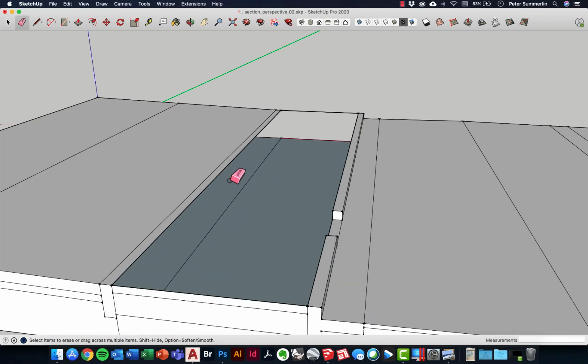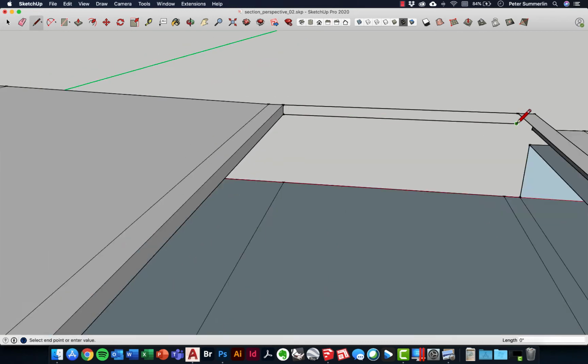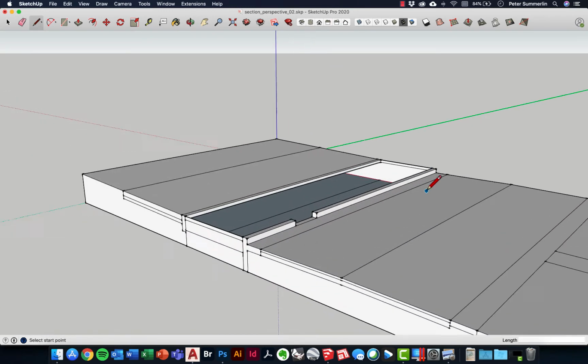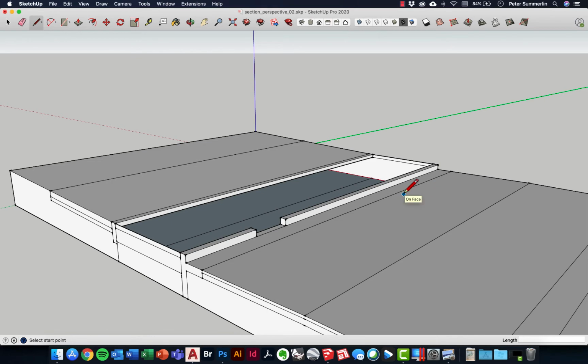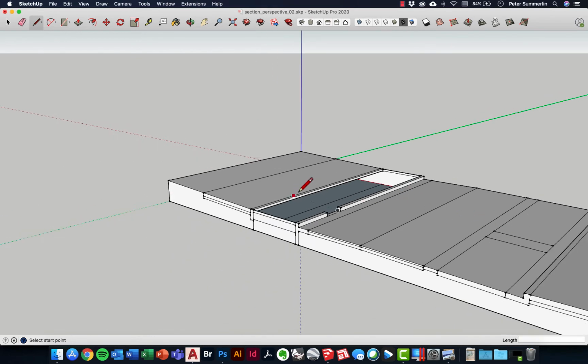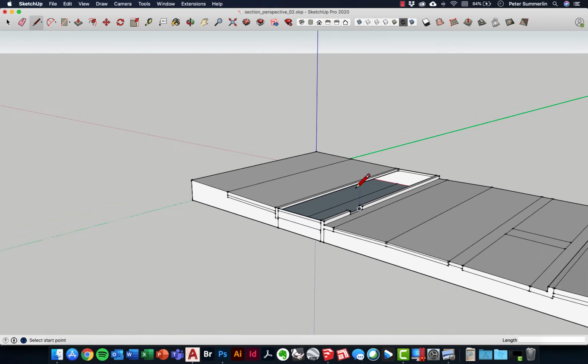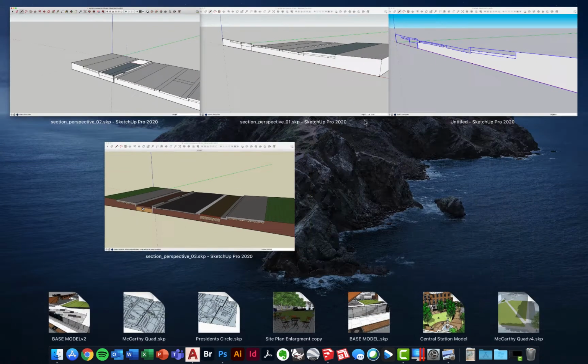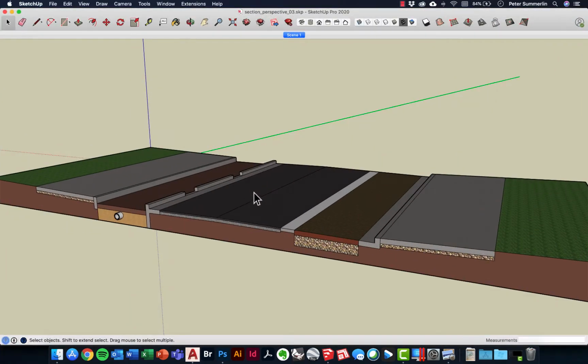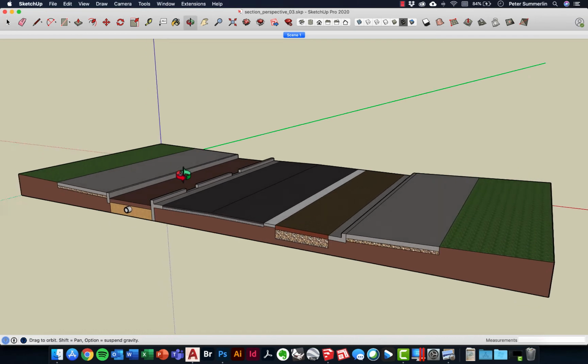Now obviously as you go through this, you're going to have to recreate some of the lines. And now, beyond just creating some of the line work and adjusting things in perspective, maybe you're creating just control joints in your sidewalks and different things like that, you're also going to want to add in materials. And so in here what we've done is added in a few materials, both on the top surface but also through the depth right here, and begin to set up our scene.